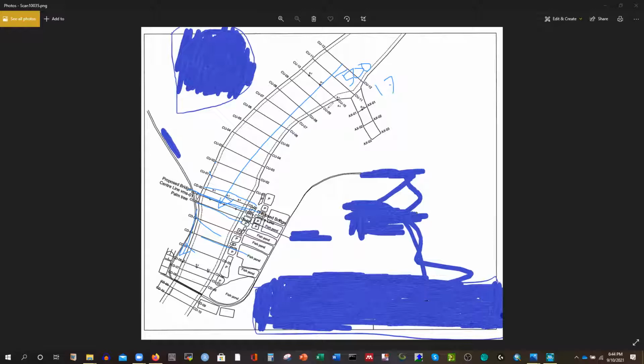And for the cross section you are inserting, the model will assume that you are inserting from left bank to right bank. So now we have an idea about which one is the left bank and which one is the right bank, which one is upstream, and which one is downstream. So at the upstream cross section here, we need a boundary condition, right?